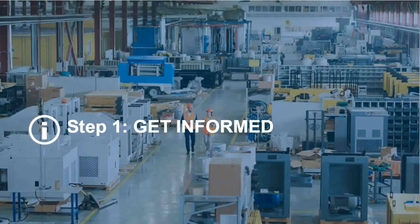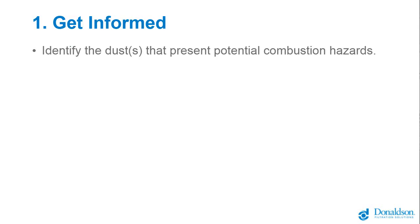So let's dive in with step number 1, gathering information about your process. Regardless if your dust is combustible or not, you want to be informed on the materials which will be handled or produced in the process. This includes understanding where dusts are produced and where they represent risks, such as overhead structural supports or transfer points within a process. Keep in mind that some materials may present different hazards when physically changed or when they are mixed with other materials.